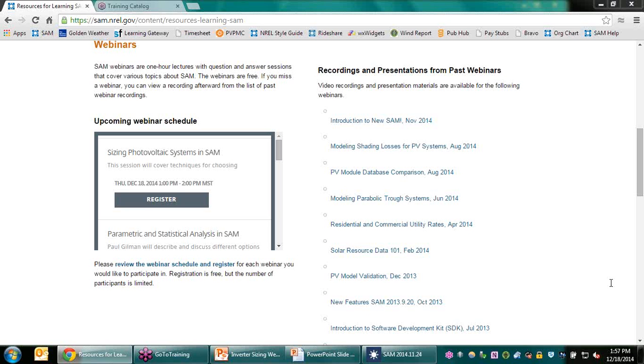Yeah, I think there was a note on the known issues page a while back for the CEC data import. Those have been addressed and I think are fixed. The other thing that can be confusing when you talk to manufacturers is that in older versions of the model we defaulted to the Sandia model, and if you didn't look closely you may not have noticed that we have multiple module databases in SAM. We have both the Sandia module database and the CEC module database, and then you can add your own via the data sheet, as you're saying.